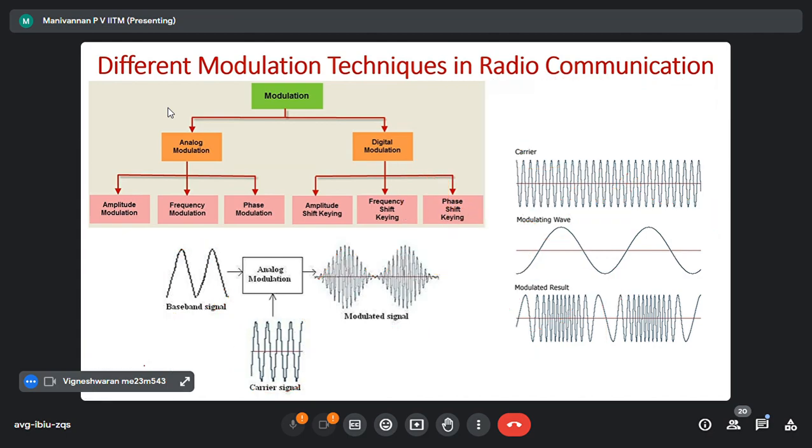So does it mean that, sir, after the transmission is done to the required destination, these waves will be again separated out? That is the demodulation. In your TV, radio, cell phone, you have an antenna, correct? But then it comes to the demodulator. First thing is it comes to an amplifier, because we know the signal picked is millivolts or microvolts, because your antenna is very, very small, a few centimeters, right?